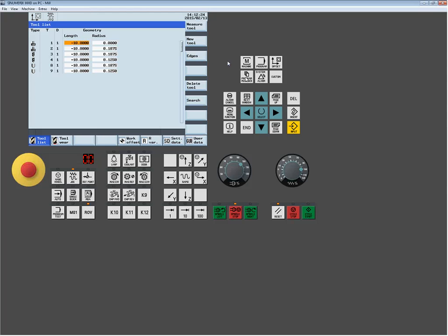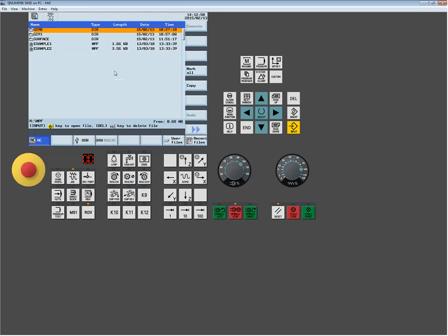It'll back me up. So I select input. I drill down into this Siemens folder. I highlight my resulting program, copy, select my NC. It's going to leave me at the folder I was last in. So now I can simply hit paste, moves the program into the part memory. So now, if I was to back all the way out, I'm back at the root directory. If I go into the G290 folder, I now see this part program.